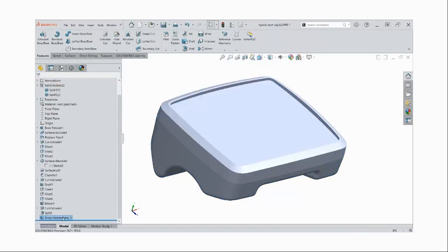it's going to get rid of whatever reference surfaces there were. So you'll see if I roll back above that, it has the two surface bodies there. And then when I roll back down, they're gone. So that's what I'd recommend using towards the end of your tree to get rid of those references so they don't confuse someone else.